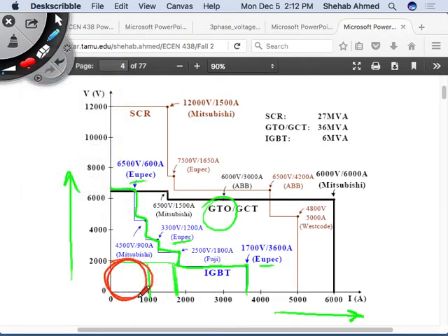Right? MOSFETs operate in this range, so up to 2,000, up to 1,700 volts. Actually, you will find some MOSFETs. Very rare, but you would find some, and then currents much less. Maybe up to 100 or 50 amps. You would not find high voltage. Actually, maybe more like this. Right, so it's low voltage, high current, up to maybe 1,000 amps or 800 amps, MOSFETs. But you cannot find a MOSFET that operates maybe here, almost 800 amps and 1,000 volts. You would not find it.